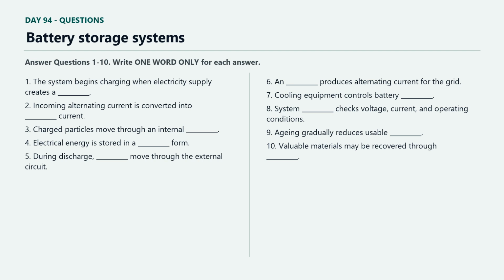Power and capacity are related but distinct: one describes rate, and the other describes amount. Operators can extend service life by controlling temperature, avoiding unnecessary extremes, and selecting an operating range suited to the task. A battery used for short frequency support may experience different stress from one charged by solar energy each day.